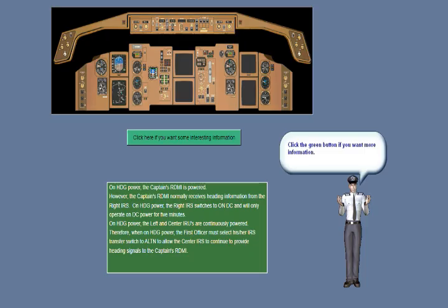The center hydraulic system supplies the hydraulic power to operate a hydraulic motor to drive the generator. The HDG is automatically activated whenever both AC buses lose electrical power in flight.